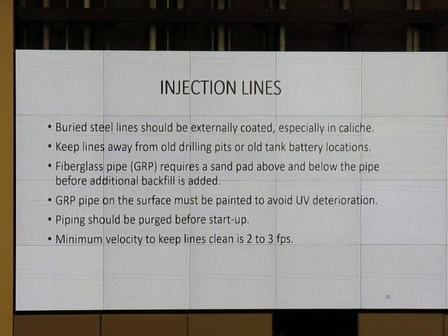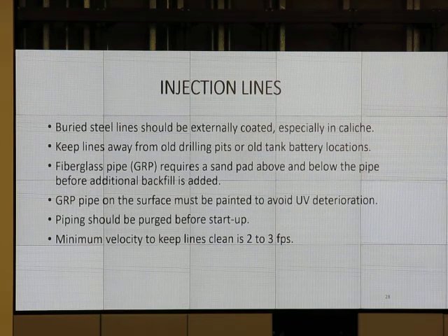Fiberglass pipe is nice, it's corrosion resistant, but it has to be padded before you put it in the ditch. You need to lay a few inches of sand in there, and then you need to cover it with sand before you start throwing in rocks and old hickory bush and everything else that they'd fill a ditch with. If you put rocks right next to the fiberglass, as vehicle traffic goes over it, you're going to punch holes in it. So the fiberglass has to be padded. Yeah, it's nice for corrosion, but it's going to cost you. There are no free lunches.